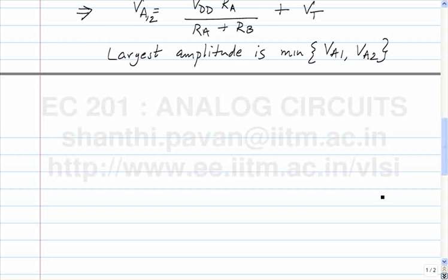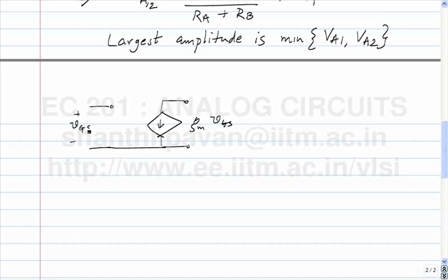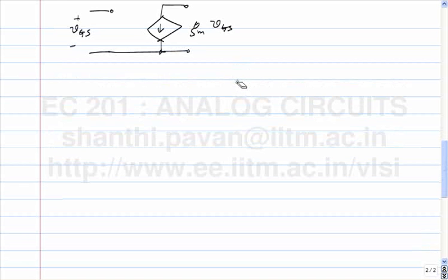Okay. So, in other words, we've seen how we take the basic transistor, which we know now to be an incremental voltage controlled current source, and in principle there is no limit to the amount of Gm you can get. Using this, we derived the common drain amplifier, which was a way in which you can get a voltage controlled voltage source. It makes sense to now figure out all the other 3 controlled sources.